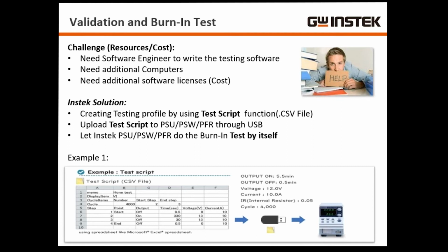So what we're trying to offer, if you need to create a test pattern or a test sequence without having to go to this expensive software to do so, is the test script function on some of our more higher-end power supplies, if you want to call it that. These test scripts allow you to program sequences that you can load onto a USB stick, and then in turn load that to the actual power supply.